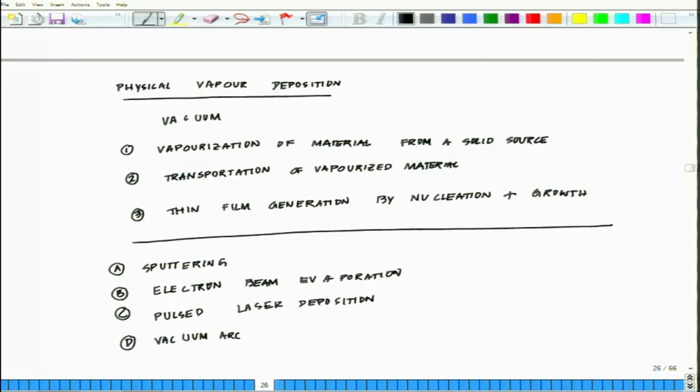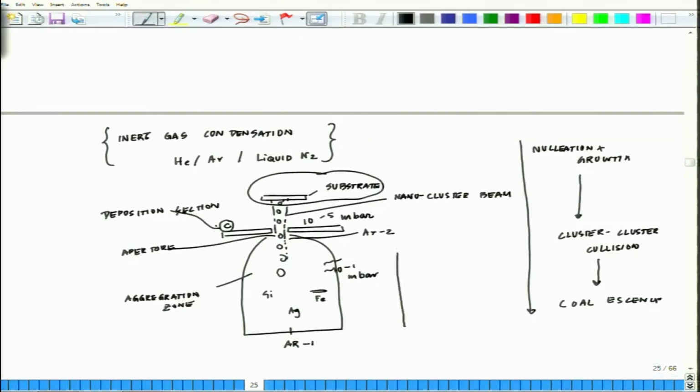So, if you follow this picture, the ejected material are then transported and deposited onto the substrate. So, you are basically making them travel through this nano slit or the aperture and getting them deposited. Okay. And there are two advantages: they lead to higher deposition rate and prevent target overheating and damage. So, this is what essentially the sputtering is all about.